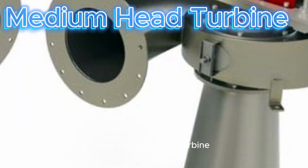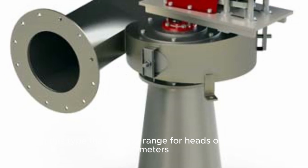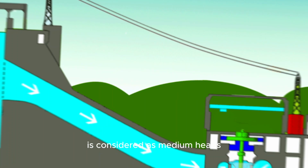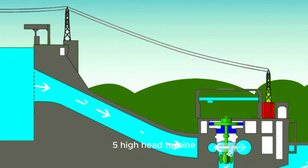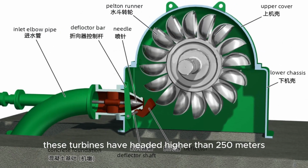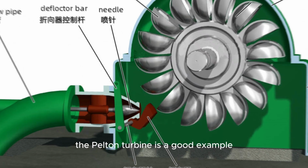Medium head turbine. In this type, the working range for heads of 45 to 250 meters is considered as medium heads. Francis turbines operate in such conditions. High head turbine. These turbines have heads higher than 250 meters. The Pelton turbine is a good example.